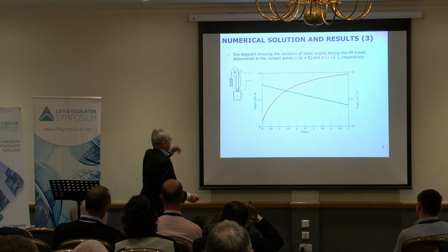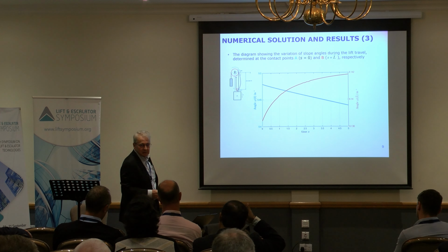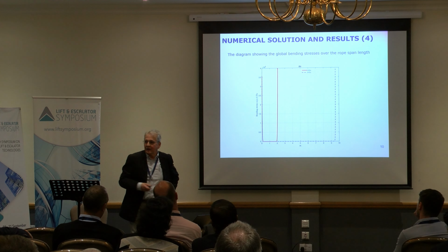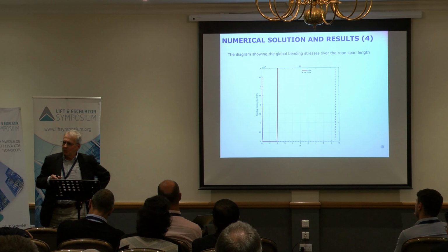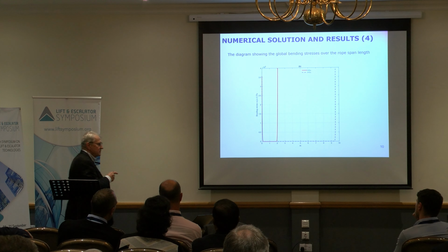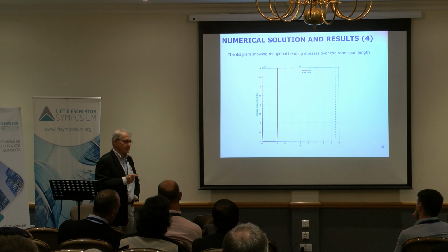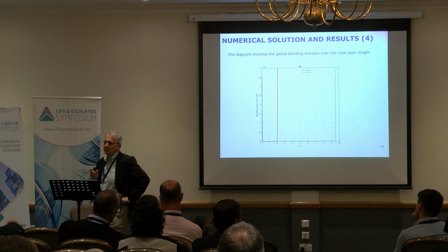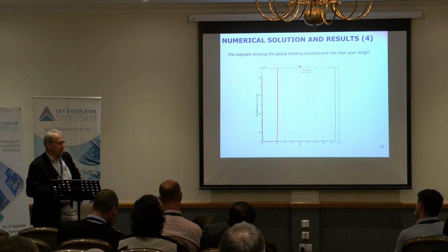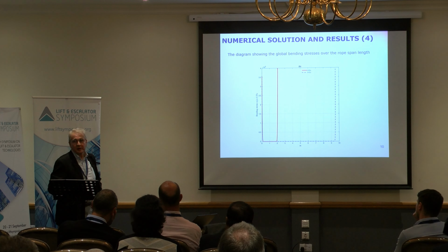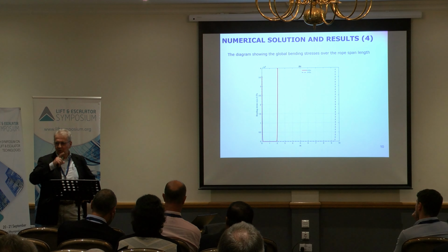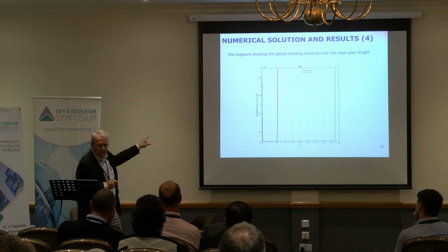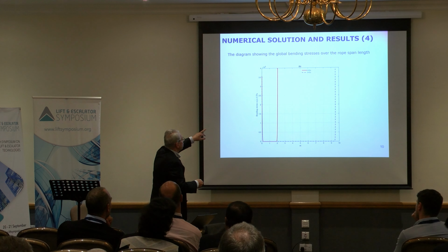Okay, so now once we have that, we can get bending stress. Again, I'm using here global bending stress formula for the wire. It is approximation. However, it is known, and it is from measurements. Klaus Feyrer, in his book, shows some experimental data. And they are not that far from those here for a given rope. Okay, so what happens here?